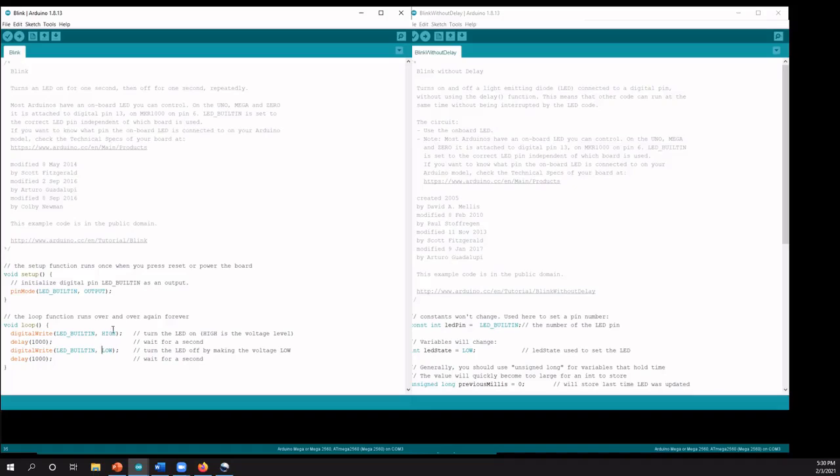What would be much better is if you could keep the loop going at its normal rate. And remember that the void loop automatically iterates thousands of times per second. So you'd like to keep that going and then just keep track of time so that every, say, 1 second, a light turns on, and then if another second goes by, the light turns off, and do something like that. That way, in the meantime, you can be controlling other circuit elements, you can be listening into other devices as fast as the Arduino can do it, and you don't need to pace everything by this one blinking light.